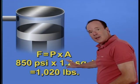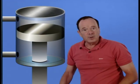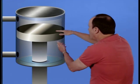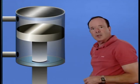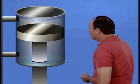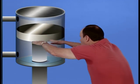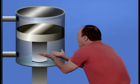Now, that's very easy, so let's take a look at a little bit more complicated one. This time, they tell you you have a double actuating cylinder and has a 3,000-pound pressure in the system. And double acting means that the piston inside the cylinder is powered in both directions. You can have fluid come in from this direction and push this piston in this direction, or you can have fluid come in from here and push the piston back in the other direction.